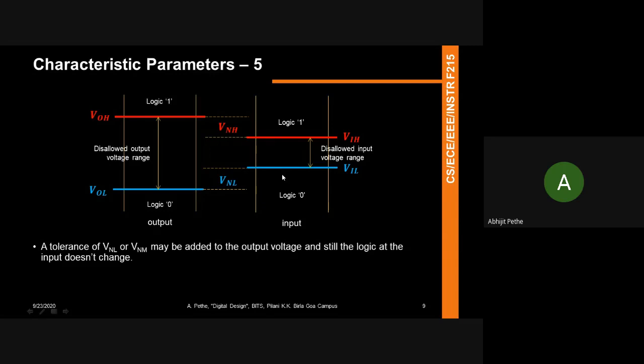So people were thinking of designing microchannels in a chip where you also feed it with coolants and reduce the temperature. What ends up happening is it takes a lot of work to cool down a chip, so eventually you don't gain anything. Whatever speed advantage you get, you're going to burn it in power. So ultimately, it is not a great way to optimize the system.